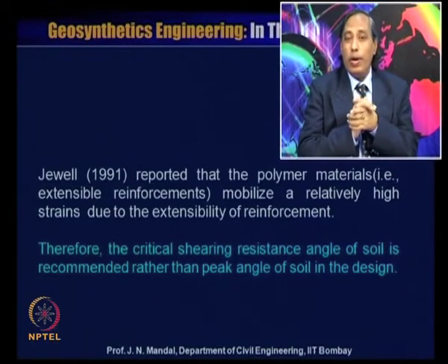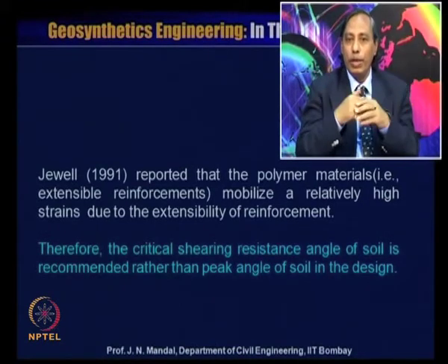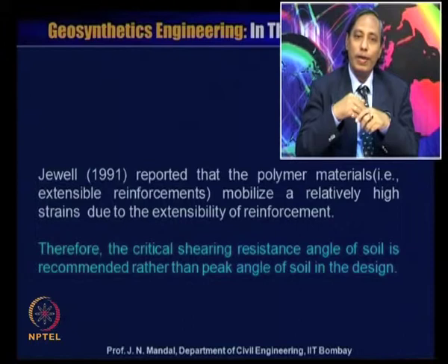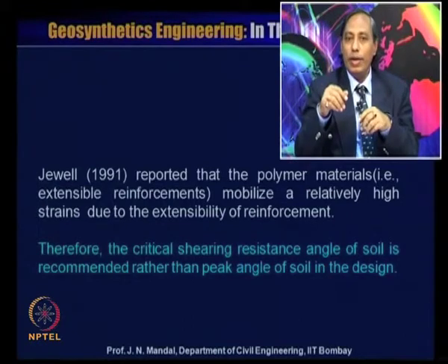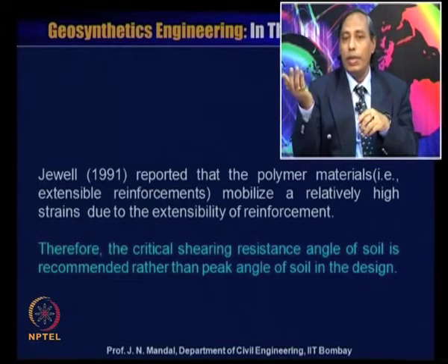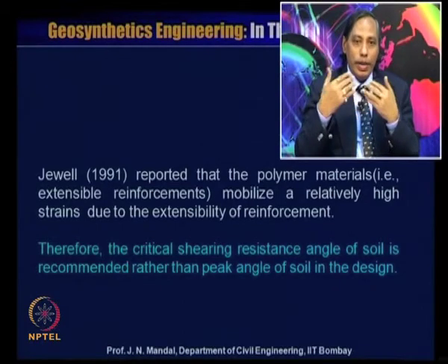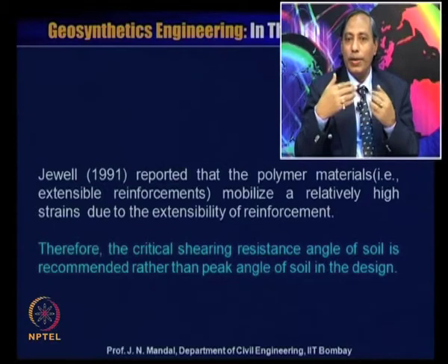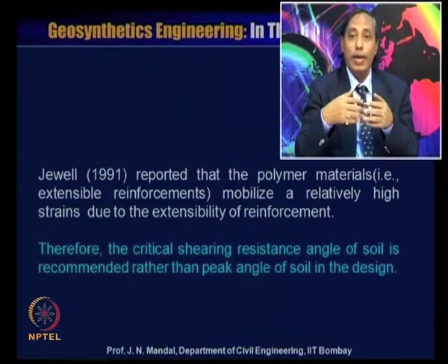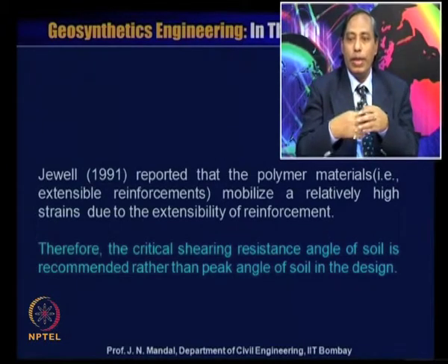Jewell 1991 reported that polymer material, that is extensible reinforcement, mobilizes a relatively high strain due to the extensibility of the reinforcement. Therefore, the critical shearing resistance angle of the soil is recommended rather than the peak angle of the soil in the design.